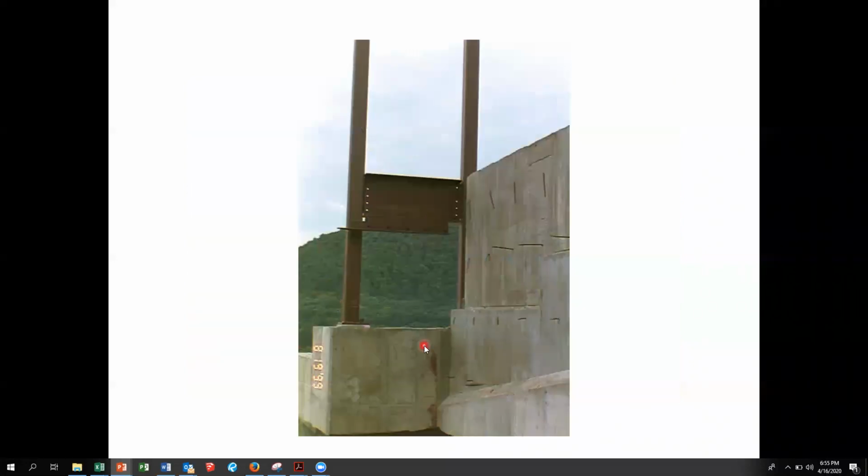There it is again, that little corner with the structural steel. This is a steel angle. You're going to see this later. This right here is a brick shelf in the concrete. There's some snap ties that they haven't broken off yet, but these are the brick shelves in concrete. This is a steel angle that is welded to this beam, and that holds up the brick.